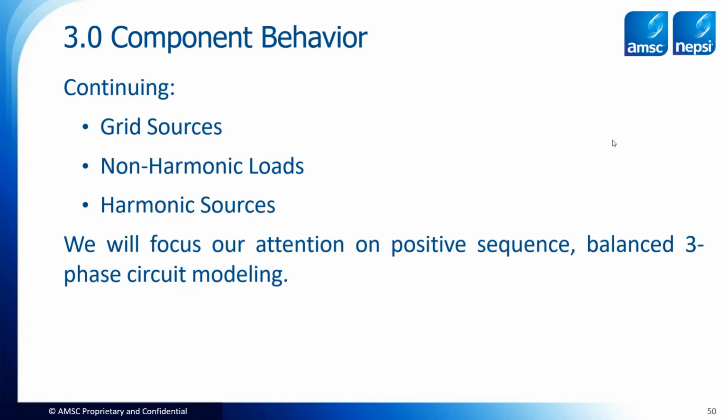For all this work that we're looking at for the presentation, we're going to focus our attention on positive sequence, balanced three-phase circuit modeling. Now, if you ever have a need for unbalanced, that's kind of a little bit of a different beast where you have to pay a lot of attention to your data, not just in the positive sequence, but in the negative and the zero sequence as well, or possibly abandoning the concept of sequence and just looking at things from a phase representation, okay?